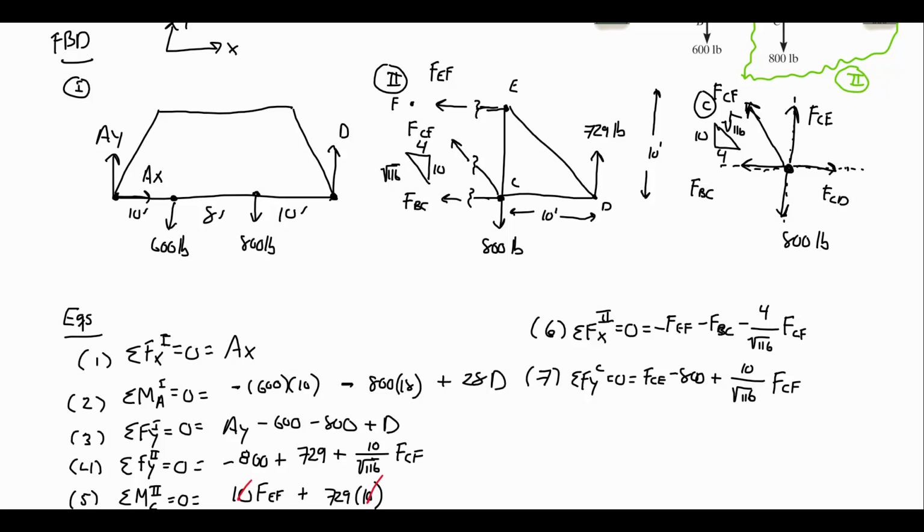Now, for internal forces, that's how I do it. Again, for the external forces like D, we found that first, and yes, in subsequent, like in picture 2, I just wrote it as 729 in the correct direction. So external forces, put those in the correct directions with their values in subsequent internal free body diagrams.